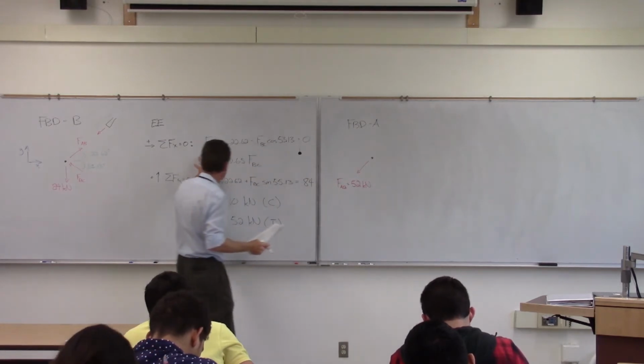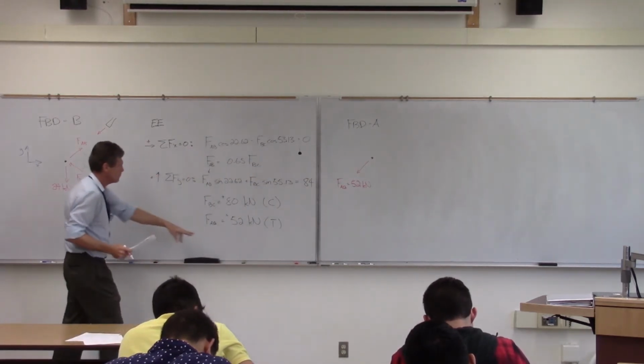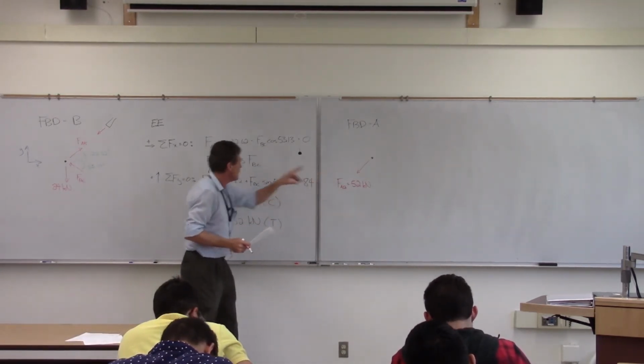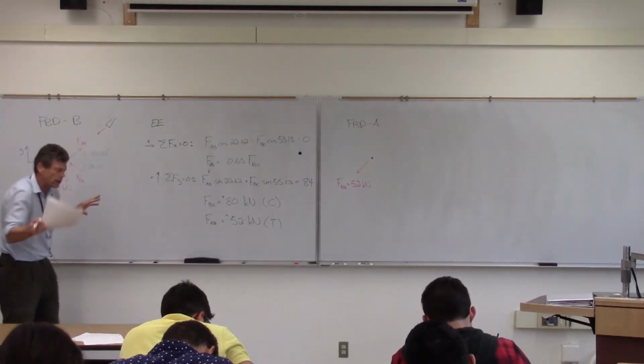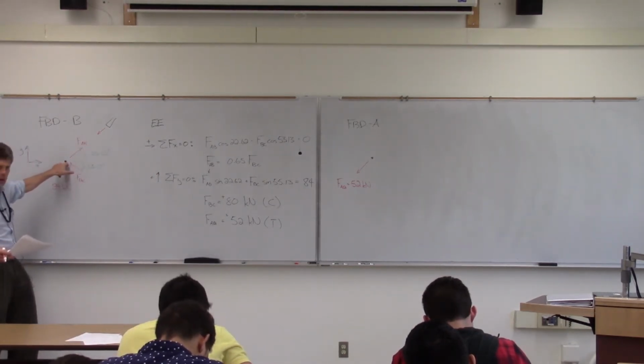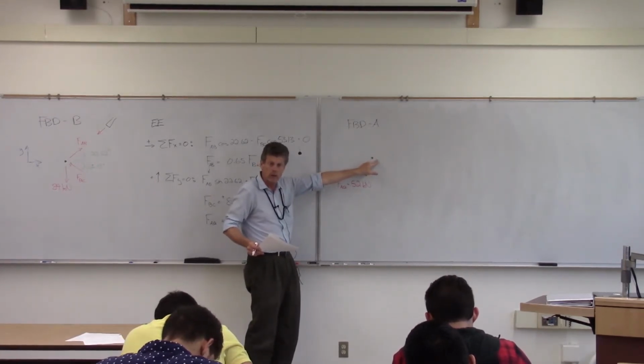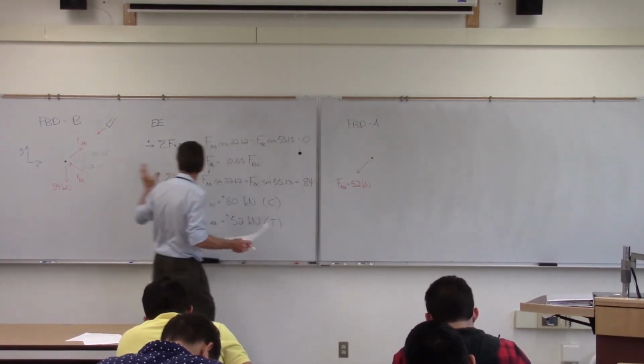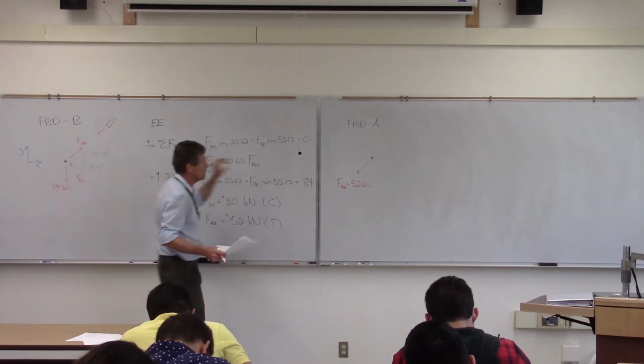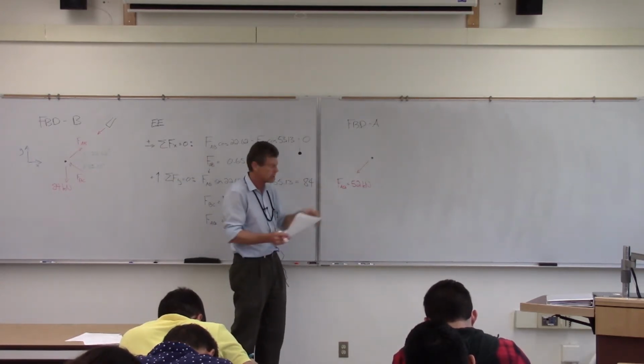Okay, so I solve for it as 52 kilonewtons. And I know, again, when we follow that member, notice that it's pulling at this joint. So it's going to be pulling at this joint too, if the member, again, is in tension. So make sure that when you start bringing those arrows, this arrow will be pulling, this arrow will be pulling if the member's in tension.